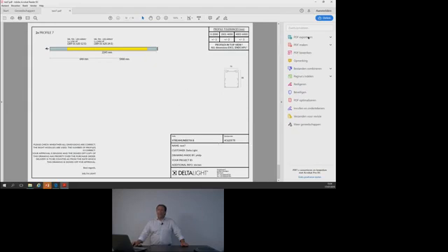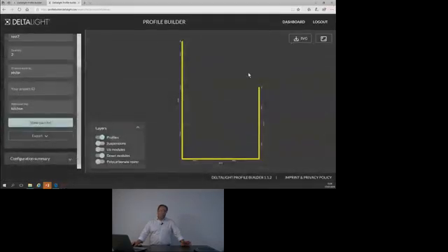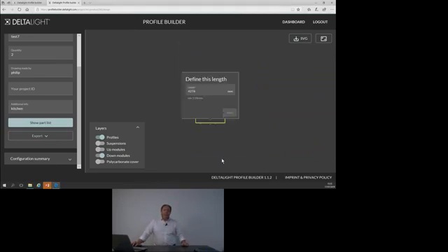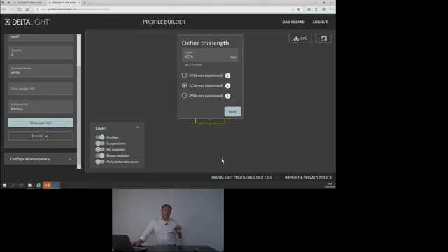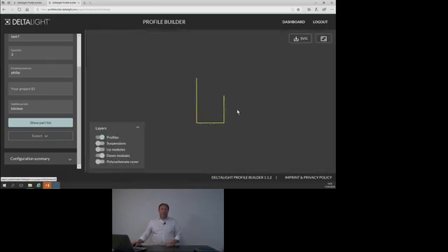Okay. If I close this, I go back to where I was before. So this is again my drawing here. Let's say that I want to change something after I have seen some mistake, for instance. So when I go back here and I press this length, so simply selecting the length, it shows me the length, the number in the middle, 4,276. I can enter something different. I can change to, for instance, 3,969. When I do next, then it will make immediately a new calculation.